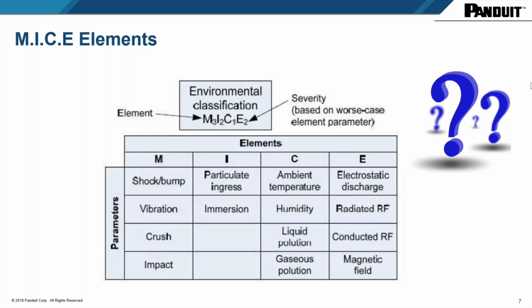There are a lot of chemicals that will attack the plastics and the TPE and all of the different jacketed material that exist on the connector and all the cable. So you need to be made aware of what type of protection my connector has to withstand, say, in an extreme chemical or a caustic environment that it is being deployed in.